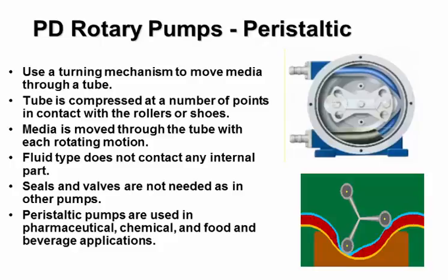For light slurries, we can, yes, chemical slurries. Oh, with screw pumps, it depends on the type and the pitch of the screw. It can be up to 80 bar, 100 bar. With some of these pumps, they're very, very high pressure. Okay, getting back to my question, where do we see these peristaltic pumps?